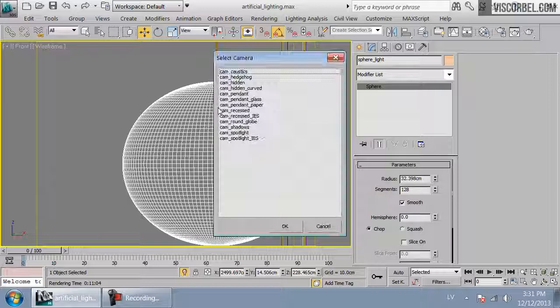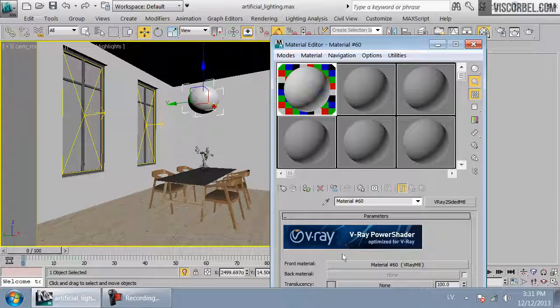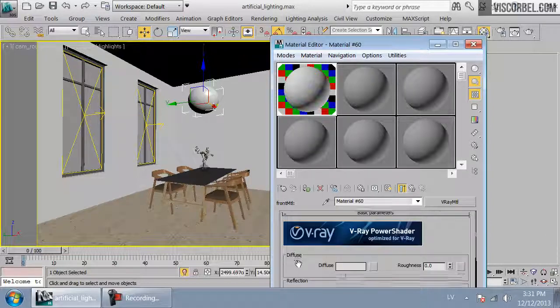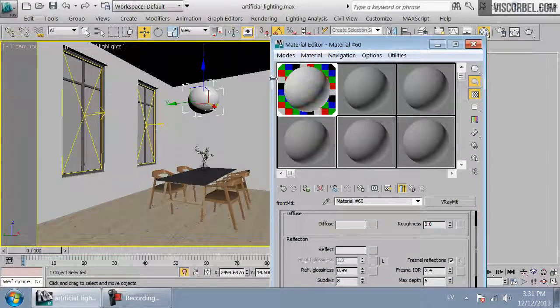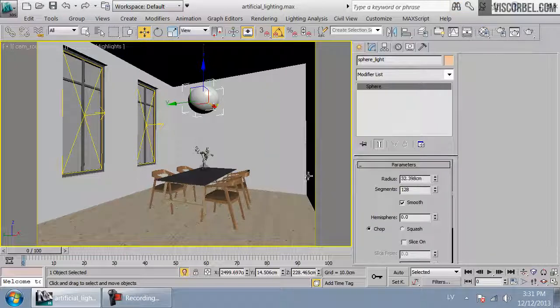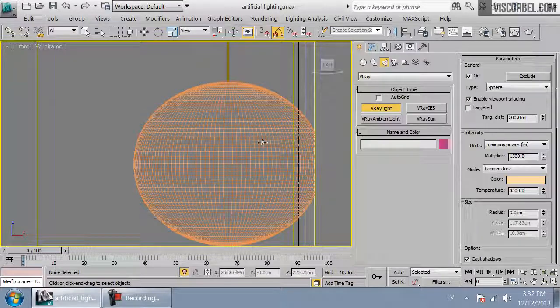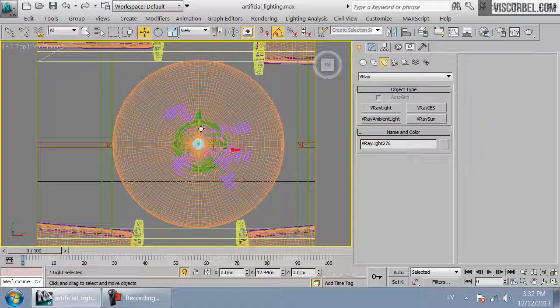So in this case I recommend creating a new material. So here's the material for the lamp, and basically it's just some simple glossy white V-Ray material set up as V-Ray two-sided to give it some translucency. And it's going to render quite fast. And in this scene I'm going to use two lights. So one bulb will be used to light the lamp itself. So let's say 3 centimeters, 1,500 lumens seems about right, position in center.